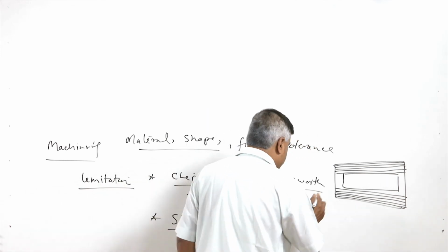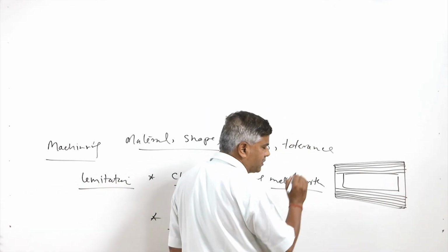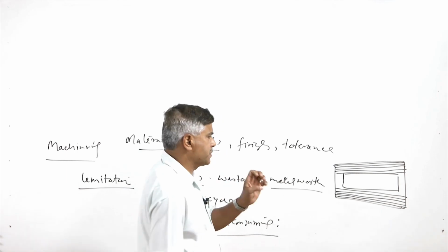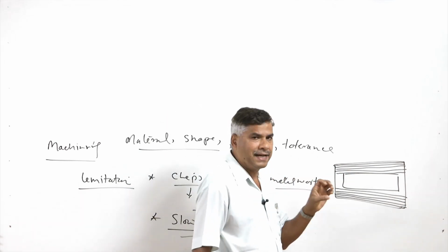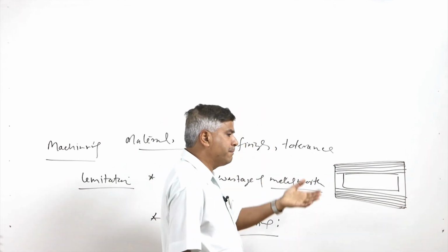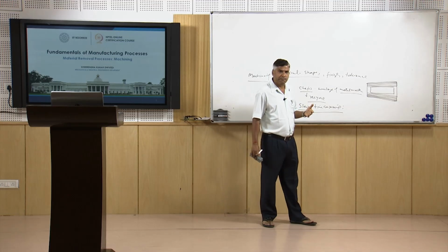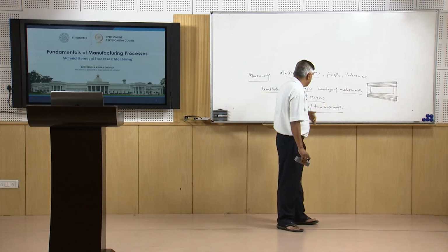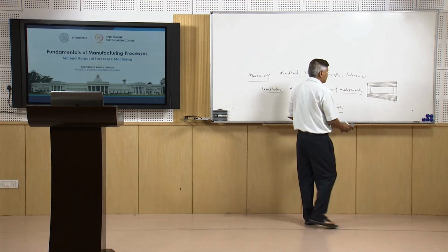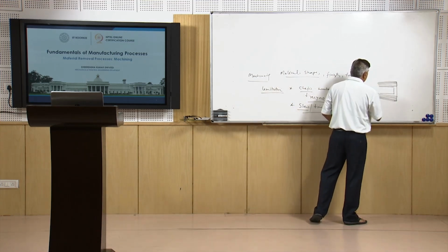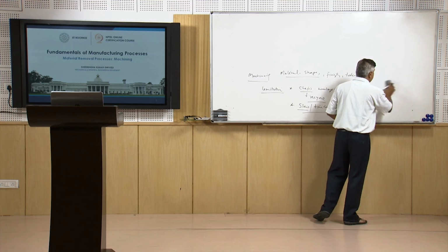To avoid such a negative aspect, the stock material is first brought close to the desired size using primary processes like forming or deformation based processes or casting, so that it requires as little machining as possible to have the desired final size and shape.